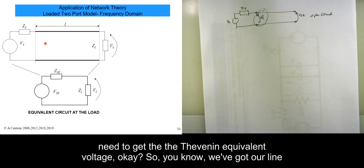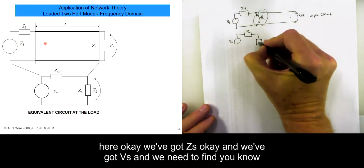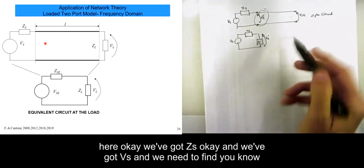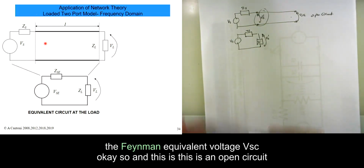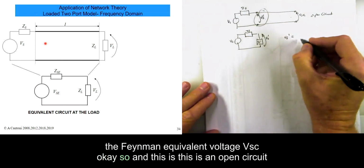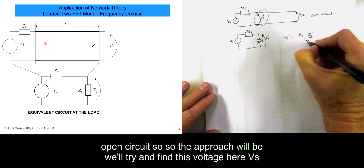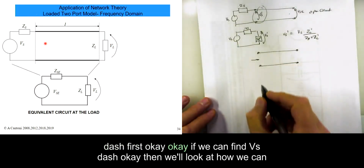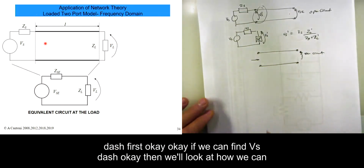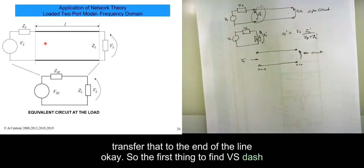Next part, we need to get the Thevenin equivalent voltage. So we've got our line here. We've got ZS and we've got VS, and we need to find the Thevenin equivalent voltage VSC. We've got VS dash, and this is an open circuit. So the approach will be we'll try and find this voltage here, VS dash, first. If we can find VS dash, then we'll look at how we can transfer that to the end of the line.